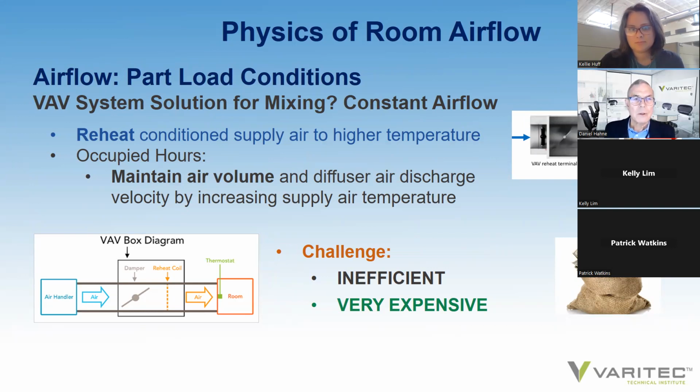What I've found with advancing 100% outside air chill beams and passive radiant cooling and heating systems is that if these systems are being considered and evaluated in early design, please make sure the full design team, the engineer, the architect, the contractor are aware of the architectural savings these systems offer. For example, underfloor air systems can now be designed to 8 and 10-inch plenum heights. You don't need 16-inch plenum heights for fan-powered terminals, and that we'll cover in the next session.